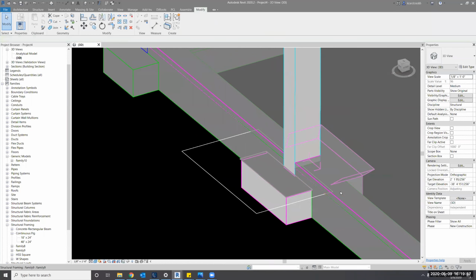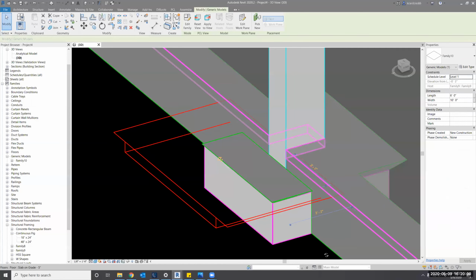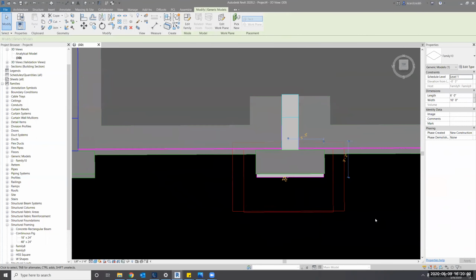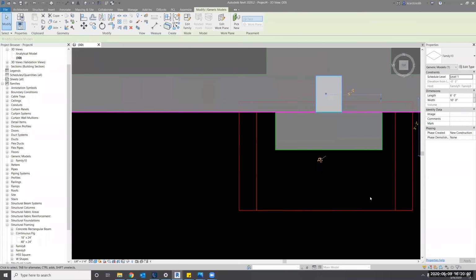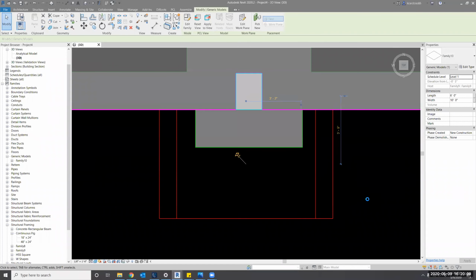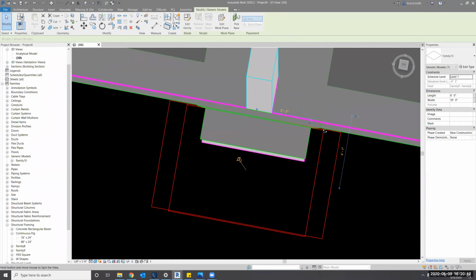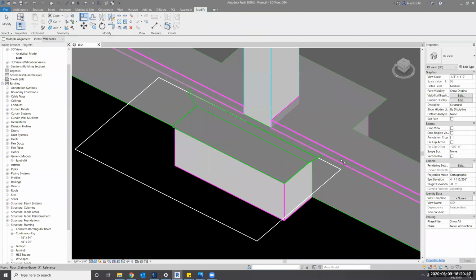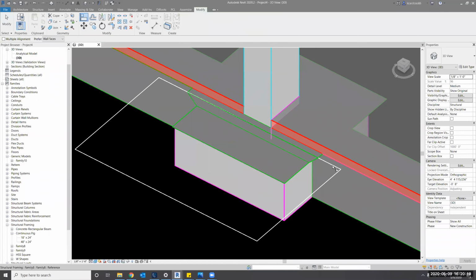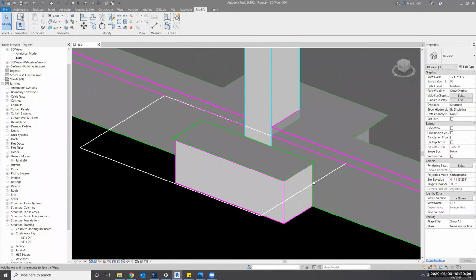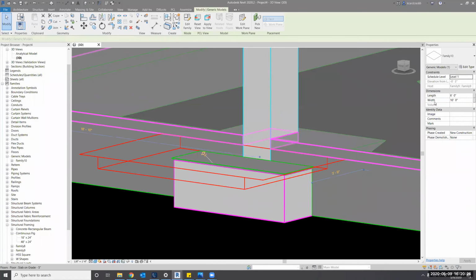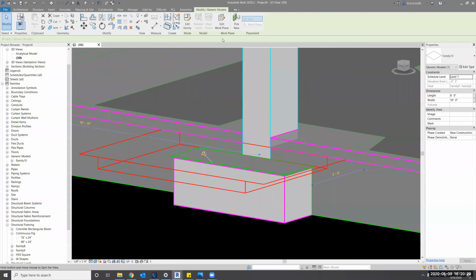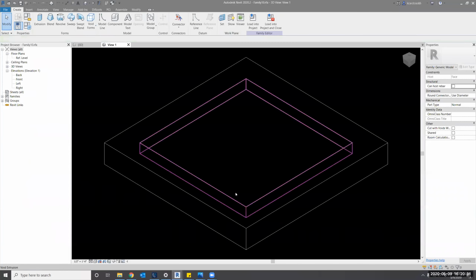But it's cutting into the family. See that? It's cutting into my beam. So you can just bring this down with your keyboard, your arrows. You can hit top here and bring it down. And then after you have your line, let's align it, AL, destination, and you can tab until you get that line. Now play with your depth. We need it. We haven't added it, or I haven't added it.